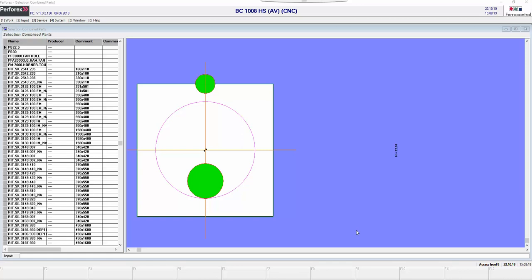I'd like to talk about how to create a good anti-rotation pilot device. One that has our pilot hole for our mill, as well as our anti-rotate drilled hole. Typically, when we make a contour, our pilot hole for the mill will actually be at the top of our contour. We'll have to move this down to the bottom so that they do not conflict.